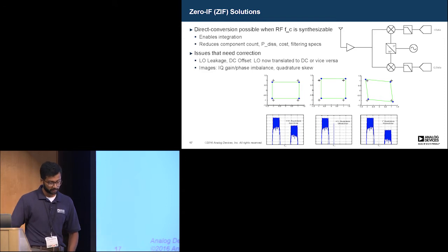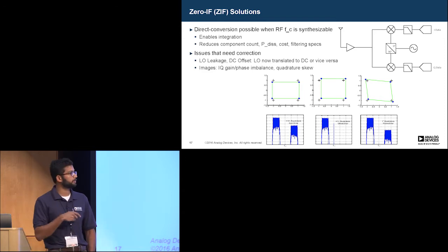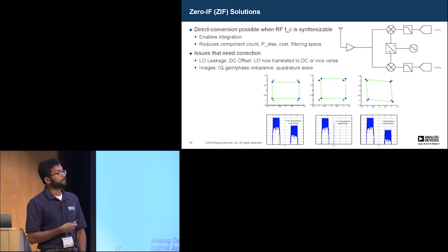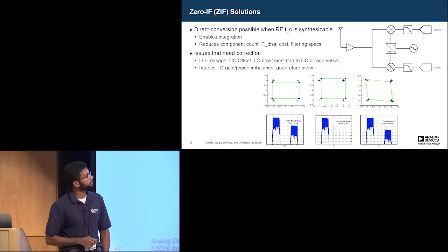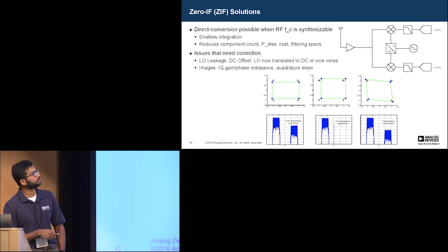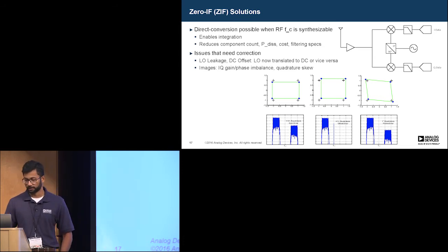It also enables integration, which in turn drives the SWaP cost down. Integration also enables you to lower the power requirements for the entire system, even for your chips. But also notice that the amount of frequency-dependent filtering is much reduced as opposed to the discrete converter IF architectures.